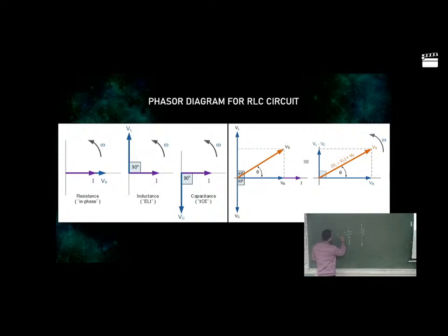We see that XC equal to 1 by j omega C, XL equal to omega L. If you have read basic networks in your first semester or third semester, whichever, you have seen that for DC analysis, in steady state, we short circuit the inductor and open circuit the capacitor. Because in DC analysis the frequency equals 0, so omega equal to 2 pi f equal to 0.